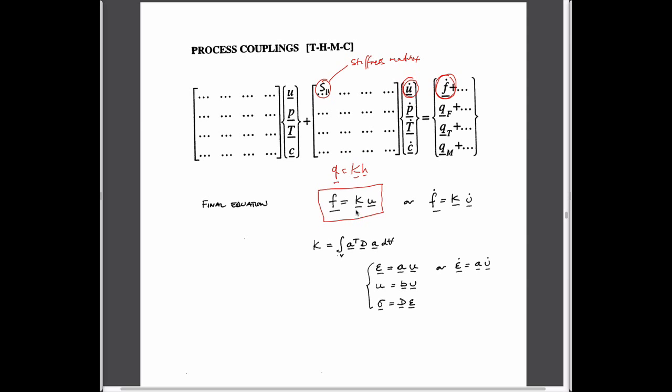And the other interesting thing that we'll find out is that the stiffness relationship, which links the nodal displacements to the nodal forces, actually turns out to be something very similar to what we've seen before. You certainly will recognize this relationship. Always positive definite and well-behaved. But now the relationships which define the A matrix are a little different. Now it links strains with displacements.